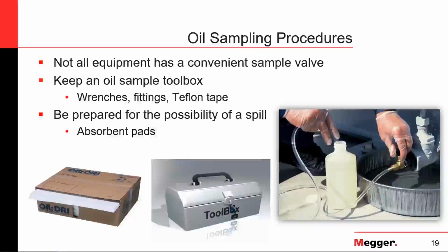I would recommend taking at least 2 or 3 times this quantity, because commonly you have to repeat your measurements, and also take into consideration that you're going to use the same oil from your sample to rinse the vessel you are using to test. So you need some extra oil for those activities, and enough oil in case you need to repeat the measurements.